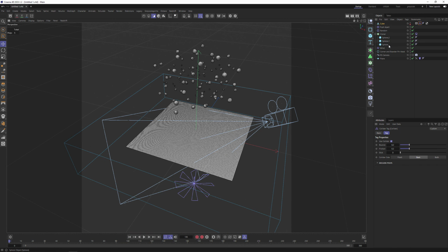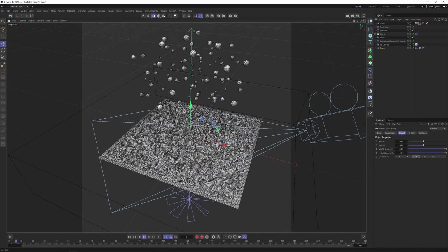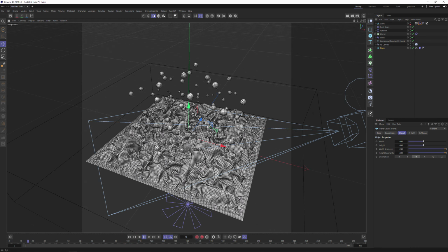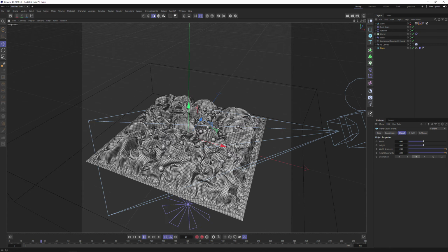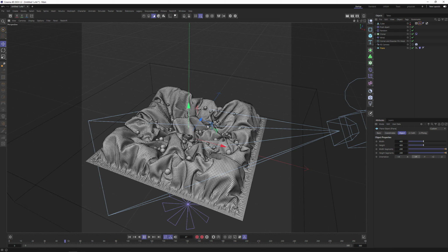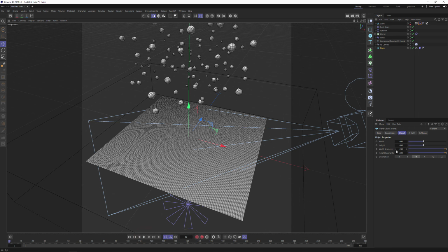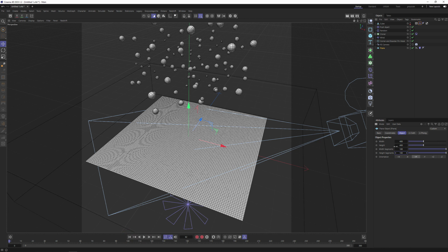Basic setup is working. Now we need to adjust for final render, increase the height segments, checking the speed and how it interacts. We have different scale of folds, but it seems that our settings work perfectly with this mesh density also. Let's go back for faster preview.